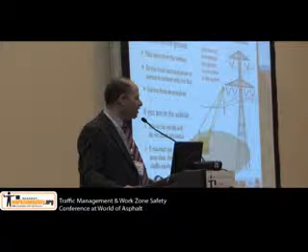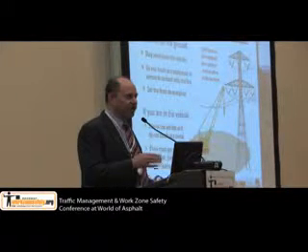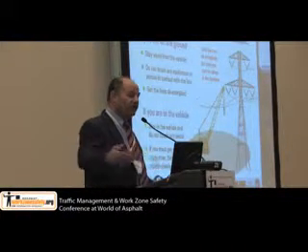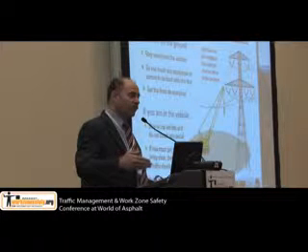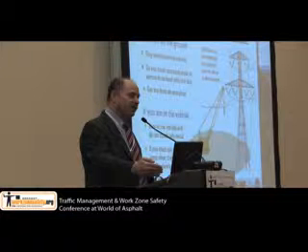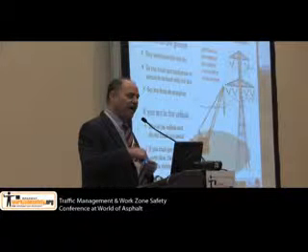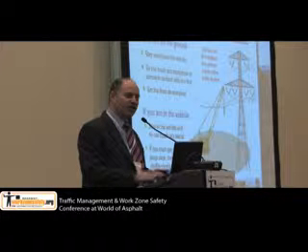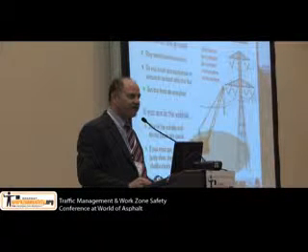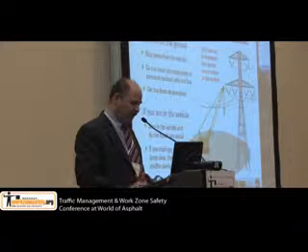Because the amount of electricity in the soil decreases rapidly from where the vehicle is. So if you step out and take a step, then the electricity can arc through your body from the higher area to the lower area. But if you're shuffling slowly away, you don't create as much difference between your feet, so you don't have the arcing.